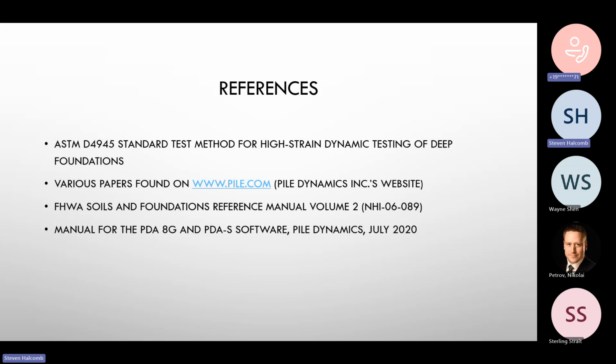Because there's as many methods to predict that as there are geotechs, I'd say. We had a consultant give us a report one time who used probably 10 different formulas and presented all 10 different chart graphs and said, well, pick the one you are most comfortable with, and I'm like, well, that's your job. That's the hardest part of my job, is to come up with that chart. It's all spreadsheets, and you can do it, but you're kind of putting your name on the line when you predict a driving capacity with depth chart.